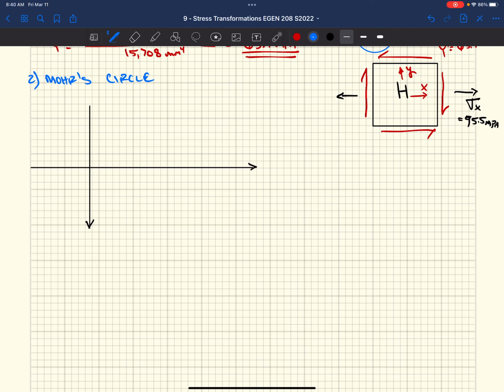Nope, not until pressure vessels. But at the rate that we're going through this class, I don't know that we're going to get to pressure vessels. But pressure vessels are cool, right? Like pipes. Anyone seen a burst pipe? You leave the hose hooked up on your house, and it bursts the pipe in the basement or crawl space. The crack is along the length of the pipe. That's because the stresses around the hoop, what we call hoop stresses, or stresses around the perimeter of the pipe, are twice that of the stresses along the length of the pipe. And so the tear is going to be along the length, because it wants to burst radially and not along the length. Pretty cool, right? So now you guys want to get to pressure vessels, huh?